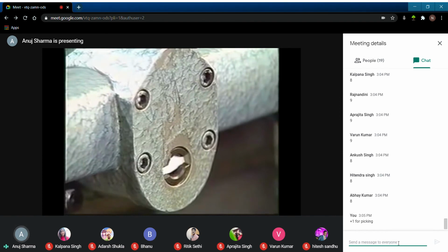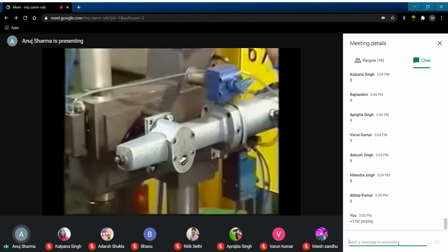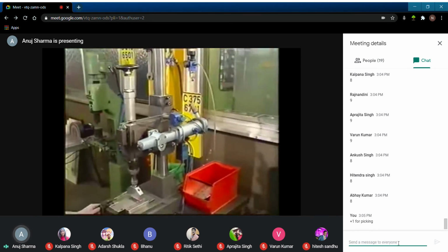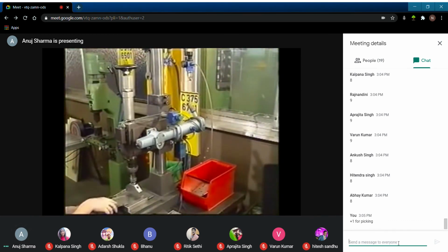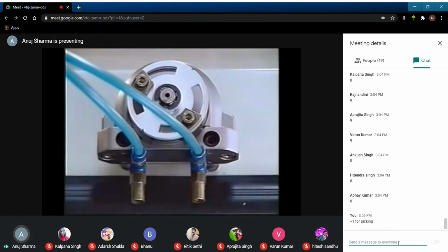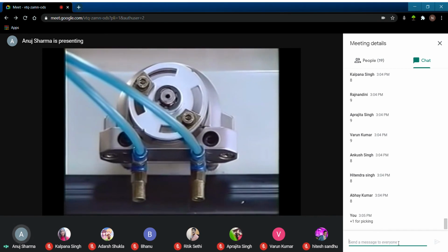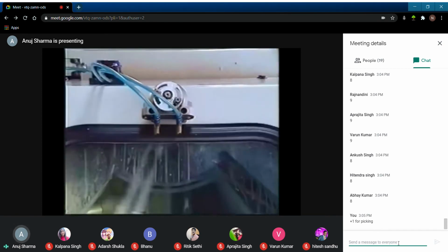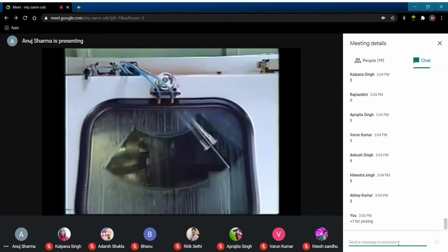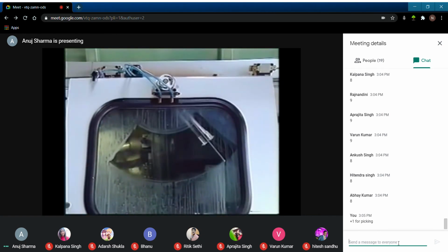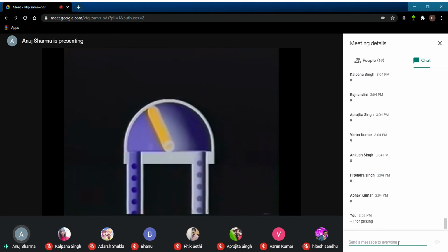This machine uses a rotary cylinder to convert pneumatic energy into a powerful force for a stamping operation. Another design is the rotating vane cylinder. In it, compressed air directly produces the rotation. It functions in the same way as a double-acting cylinder in that it has fixed stops at both ends of the stroke and performs work in both directions. In this type of cylinder, the angle of rotation is adjustable.